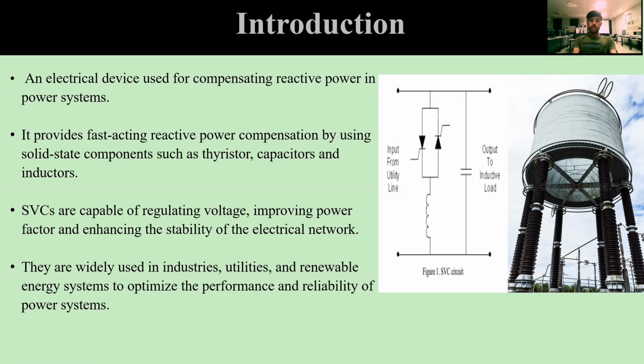Unlike other devices that use moving components, whose response is slow, the SVC using solid-state devices has a very fast response, low losses, and very low delay. They are capable of regulating voltage, improving the power factor, and enhancing the stability of an electrical network.